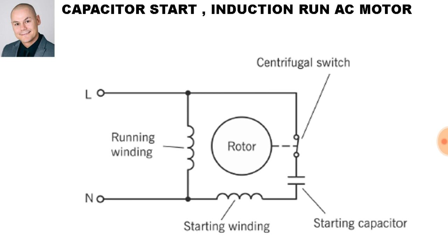Here we have a capacitor start induction run AC motor. This is a single-phase motor, and therefore it only has one sine wave, which means there is no phase shift. So the big disadvantage of a single-phase motor is that it is not self-starting.